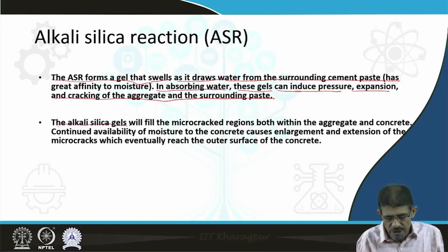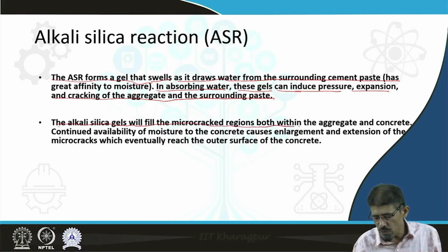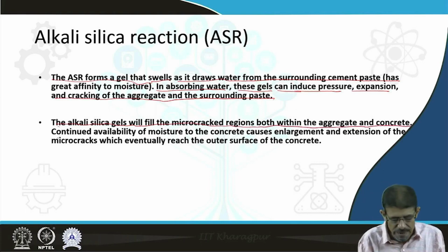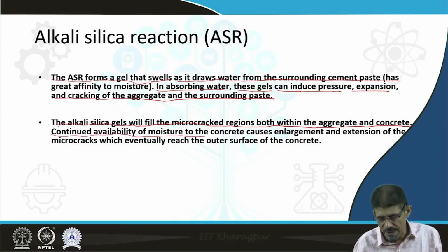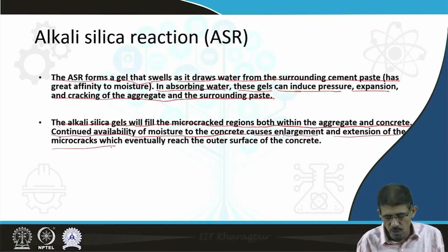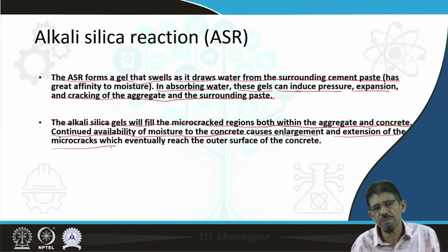The alkali silica gel will fill the microcracks both within the aggregate and concrete, and continuous availability of moisture or water causes enlargement and extension of such microcracks in the form of fractures, fissures and a fracture network, and finally results in reduction in strength or bearing capacity of concrete.